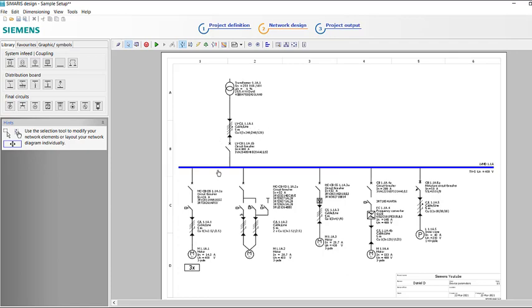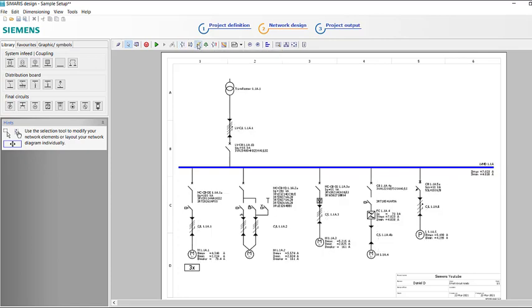Again, this tool, the reason we were doing this was for our short circuit calculation. If we hover here, single line diagram with short circuit load, and click on this button. Now we can see the IK max and IK min of each of these loads, and we can see our overall IK max short circuit here, 7 kA roughly. So in just a few clicks, I can get all my devices, and what I can also get is my cable sizes and my short circuit calculations done for me.